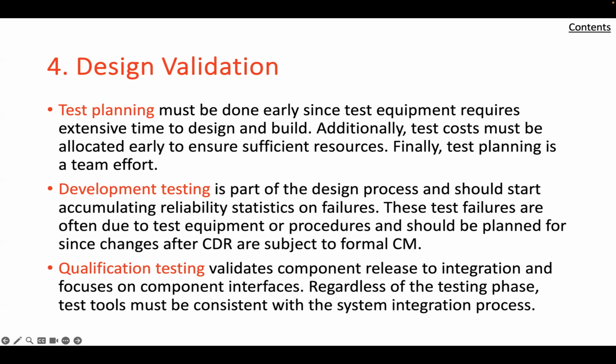Planning the test of components to validate their design and construction is an essential part of the overall test and evaluation plan. It covers two types of tests: development testing during the component design process and unit qualification testing to ensure that the final production design meets specifications. Component test planning must be done during the early part of the engineering design phase for several reasons.